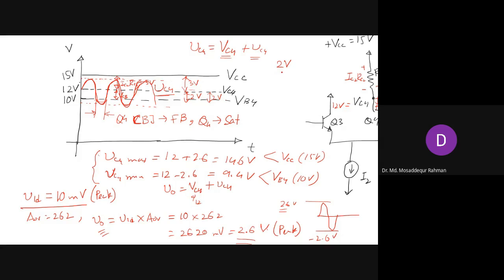So the maximum gain also, you can see that if your circuit is designed like this, and you have 2 volt of maximum signal swing, and your input voltage is 10 millivolt, that is 0.01 volt, you can have a maximum gain of 200. So if you want to accommodate this signal of 2.6 volt, you have to increase VCB to at least 2.6 or greater than this. So let's say we want an output signal that has a maximum swing of at least 2.6 or greater.